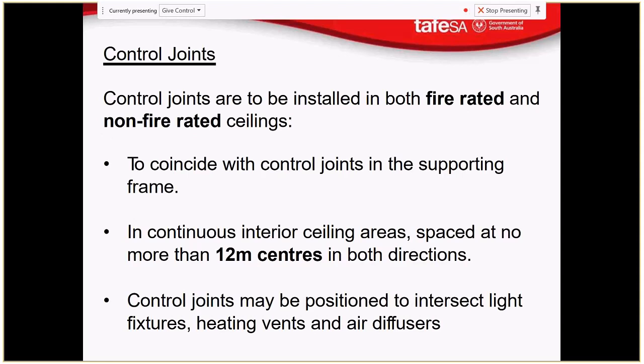Yes. Well, when we have really long runs of ceiling, because buildings do this a little bit, almost we can't see it, but they're doing that a little bit, and we have a really long ceiling, there's a high chance it will crack somewhere. We want to control where that crack happens. We don't want that crack to just happen anywhere. We've decided, right in the middle there, we want a joint that's going to crack right through the middle. Okay.